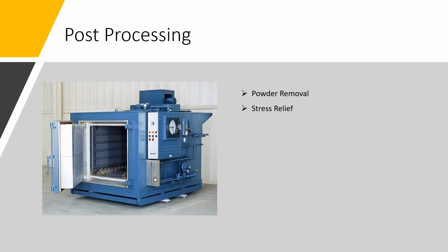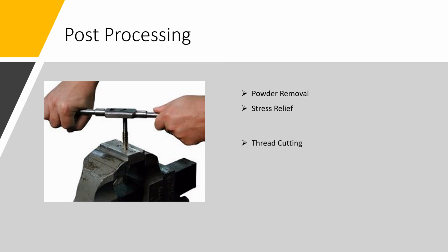The rapid heating and cooling the material is subjected to during the SLS printing process leads to internal stresses being induced on the component. The part must be left on the build plate and then placed in an oven or similar to relieve the stresses. In practice, a manifold will have threads to hold various fittings and valves. The threads should be cut during the post-processing phase.